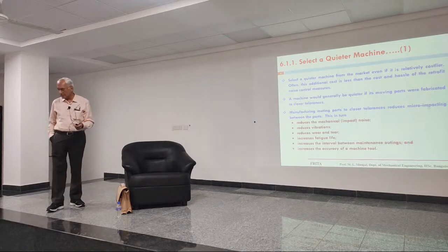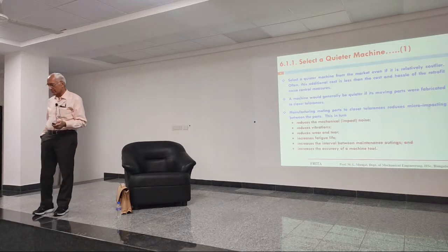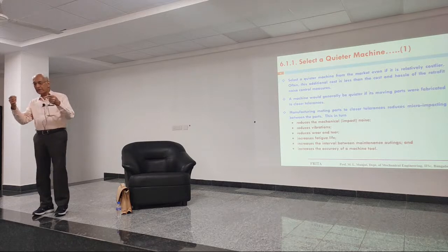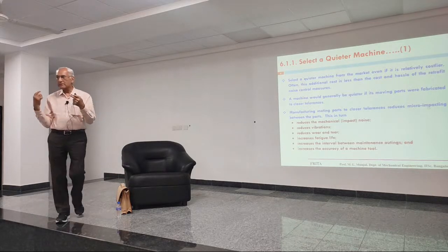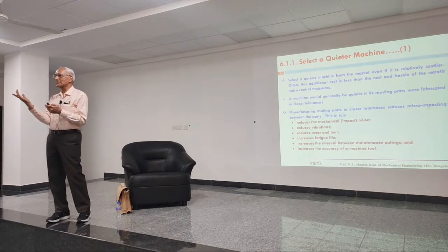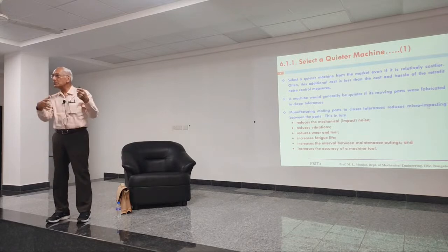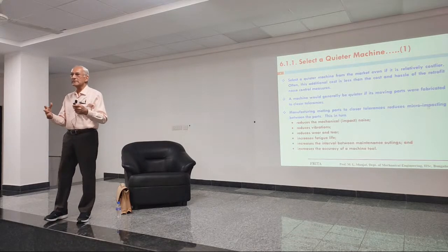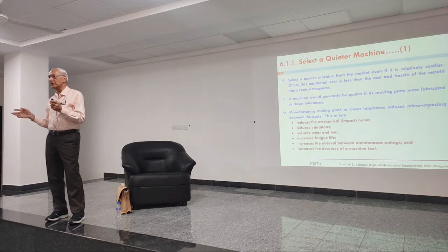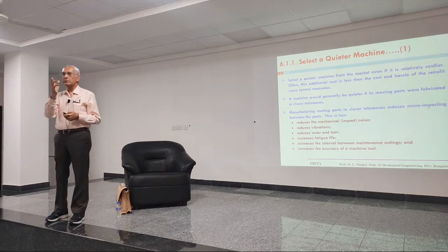This is something in India for which we are ourselves responsible, and that's why most of our machines are noisier. Because when we make fabrication drawings, we unnecessarily put additional tolerance. Because we say that anyway it will be cheaper, because when tolerance is more, the person doesn't have to be too careful, and things can be done faster. But this is a flawed position. Because in the long run, you are going to pay a very high price for doing that kind of thing.